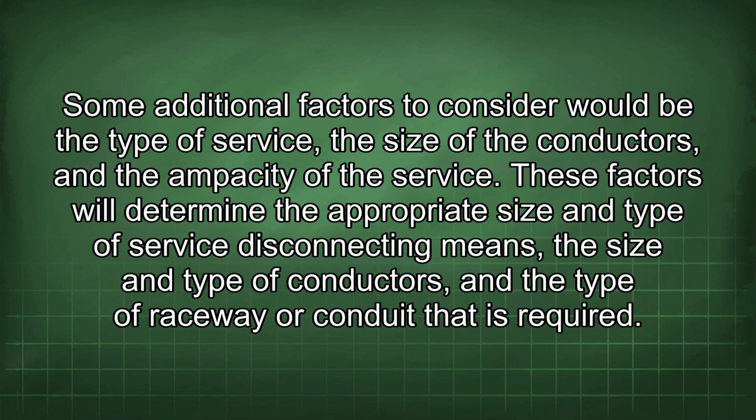Some additional factors to consider would be the type of service, the size of the conductors, and the ampacity of the service. These factors will determine the appropriate size and type of service disconnecting means, the size and type of conductors, and the type of raceway or conduit that is required.